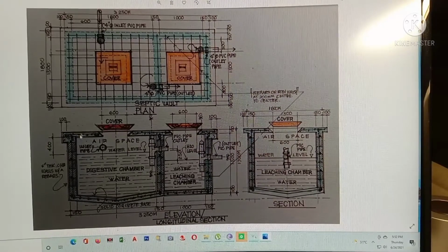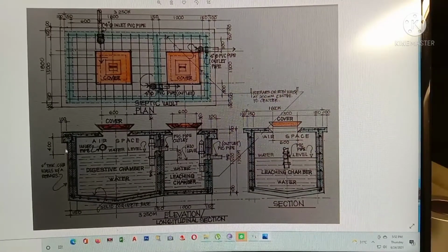So with the hollow blocks also, like our house, there's also a need for reinforcing bar. Why? So that the wall will not collapse. Whatever pressure inside this water tank, these walls here will not be broken, will not be damaged, because this is also reinforced with rebars. There are rebars here, both horizontal and vertical. So with the flooring here, you have to put rebars also.